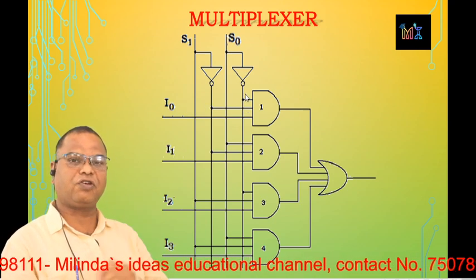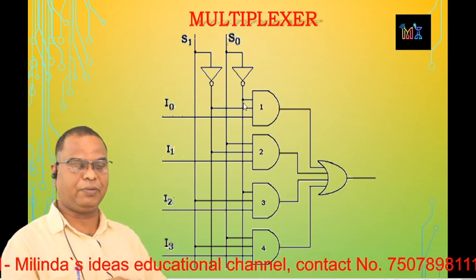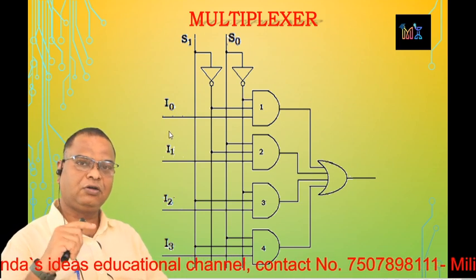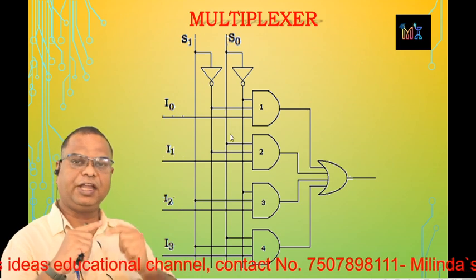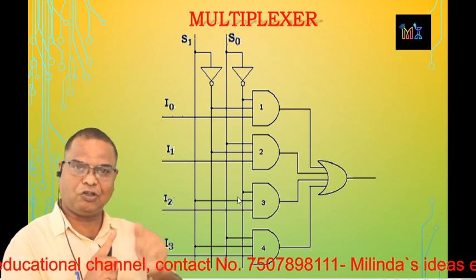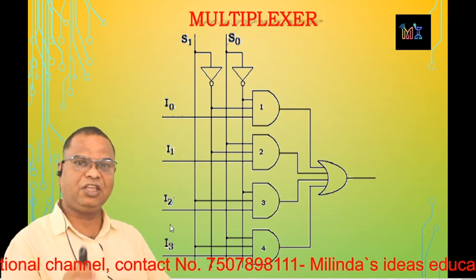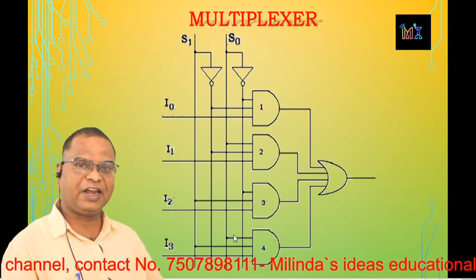So the inputs for the first AND gate are I0, S1 complement, S0 complement. The inputs for the second AND gate are I1, S1 complement and S0. The inputs for the third AND gate are I2, S1, S0 complement, and the inputs for the last AND gate are I3, S1 and S0.